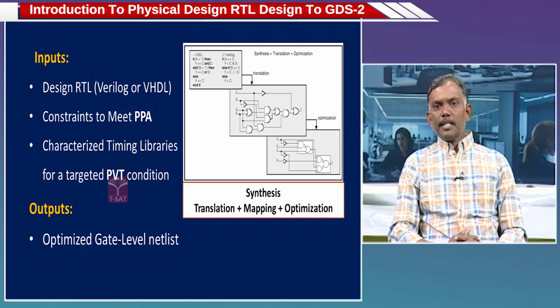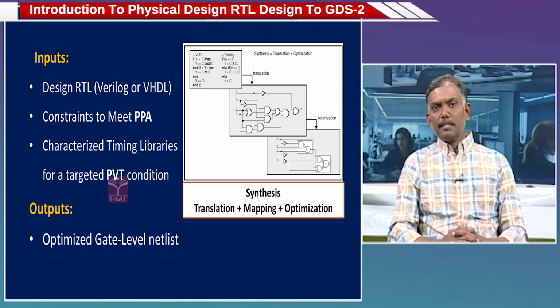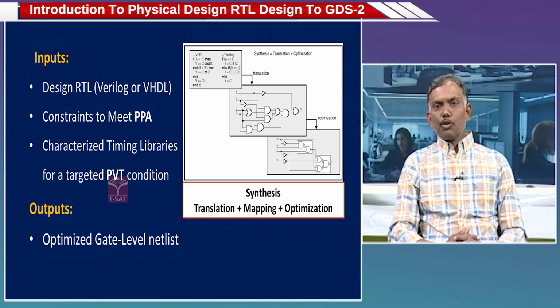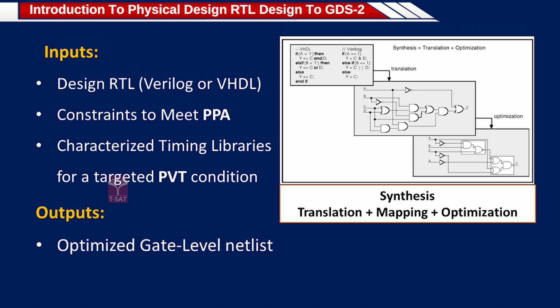Let's assume, for understanding purposes, that each gate takes a uniform delay, a common delay for each gate. Every gate takes 2 nanoseconds in the slow corner for a given input transition and output load. In a typical corner, let's assume each cell delay is 1.5 nanoseconds. And in the fast corner, where you see less delay, let's assume 1 nanosecond for each gate. So 2 nanoseconds in slow corner, 1.5 in typical and 1 in fast corner.